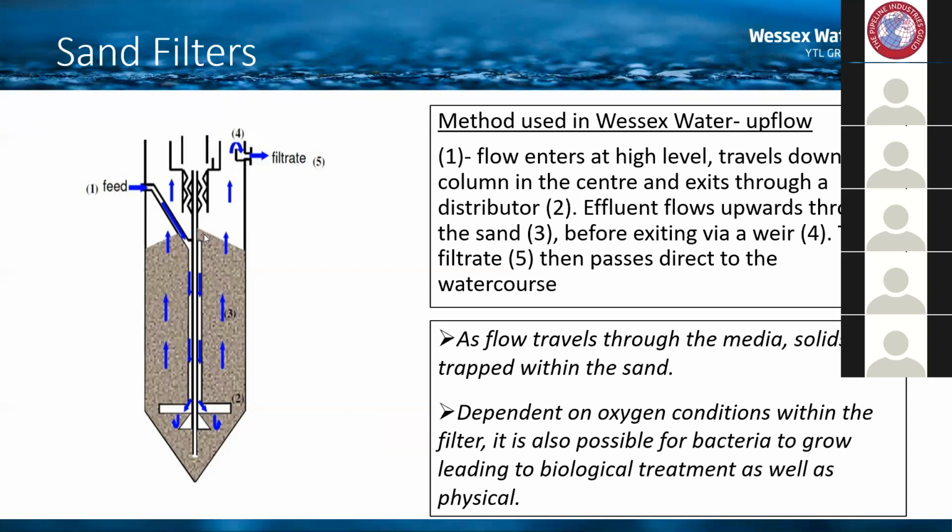So in this system, the flow is constantly moving up through the bed, and the sand is constantly getting cleaned and moving down. And depending on the setup, it's also possible that you can aerate these sand filter systems, and it does provide ammonia treatment as well, because you can get a biofilm growth on the sand particles.